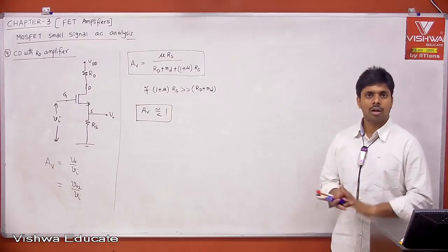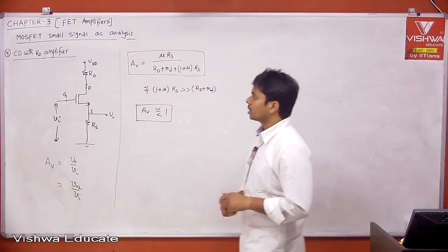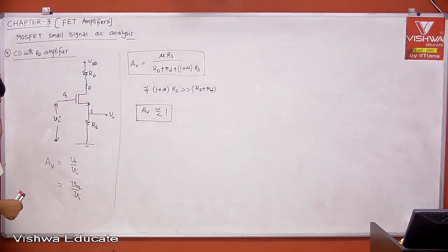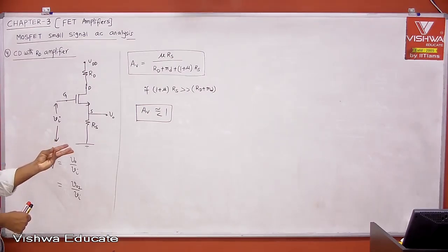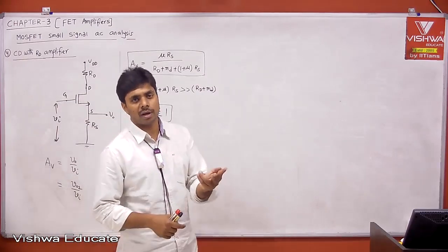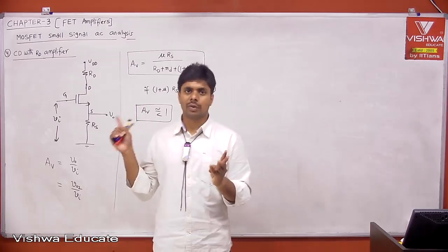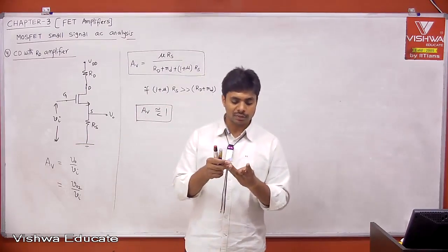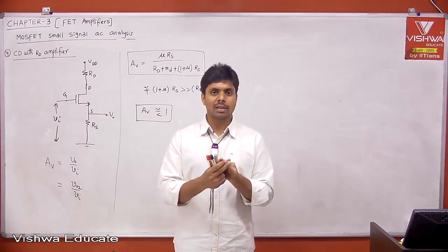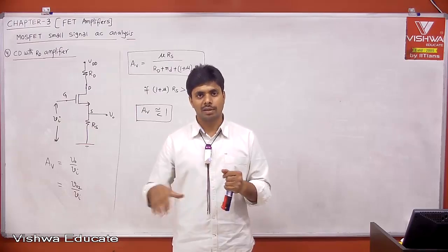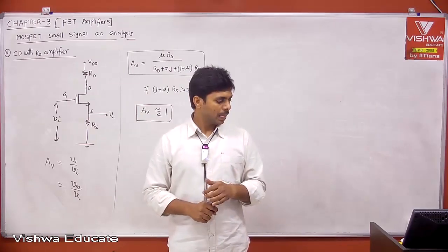Almost the session is over. Then let's continue in the next session to see the output impedances. Whatever we had seen till now: common source amplifier, CS with RS amplifier, CD amplifier, CD with RD amplifier. For all 4 configurations, we need to find output impedances. But instead of finding them individually, let's calculate for CS with RS and CD with RD, then take the other 2 conditions, RS equal to 0, RD equal to 0, and you will get the other 2 remaining derived configurations. Okay.